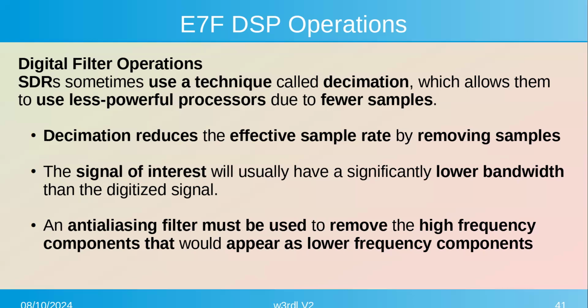When you do that, you have to worry about aliasing, because now you've got samples at a much higher rate, even though you're throwing some of them away. They were actually sampled at a higher frequency, and you want to look at it at a much lower frequency, so you have to filter those higher frequencies out, so you don't effectively get aliasing again.